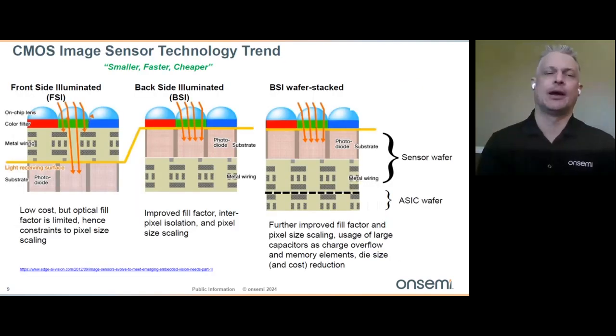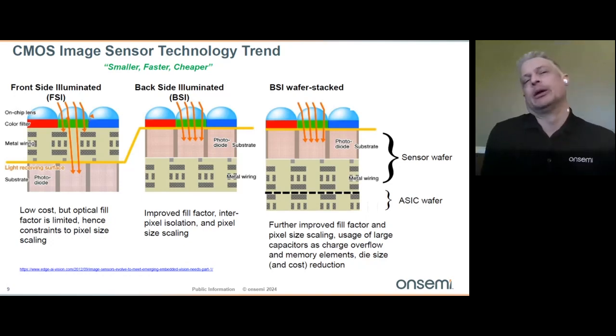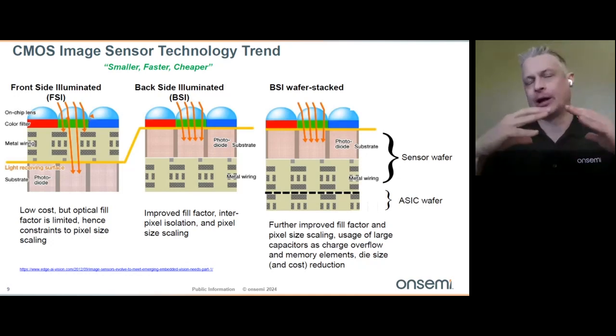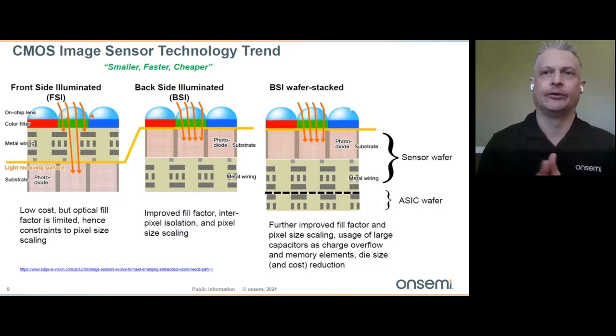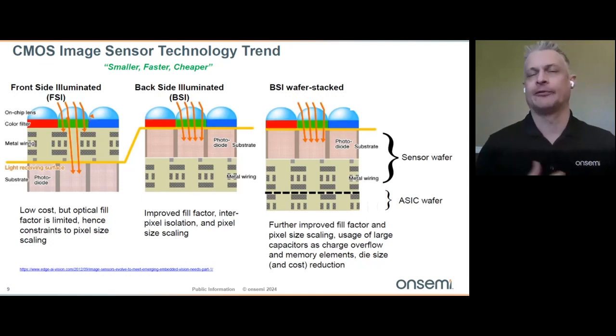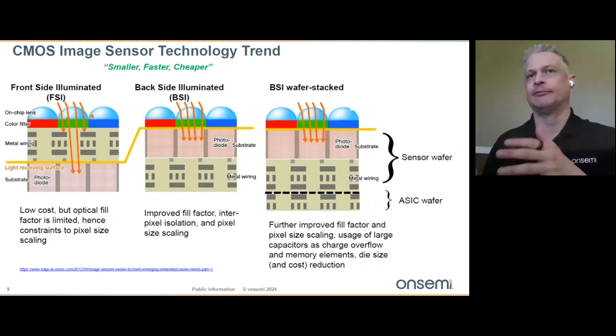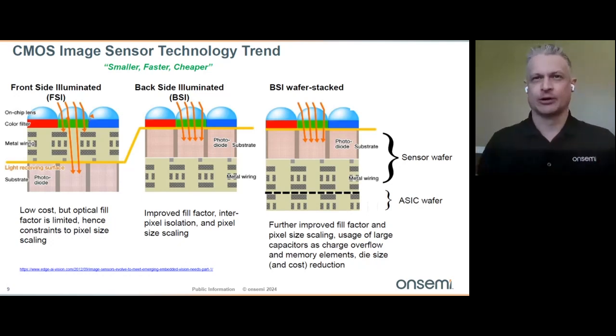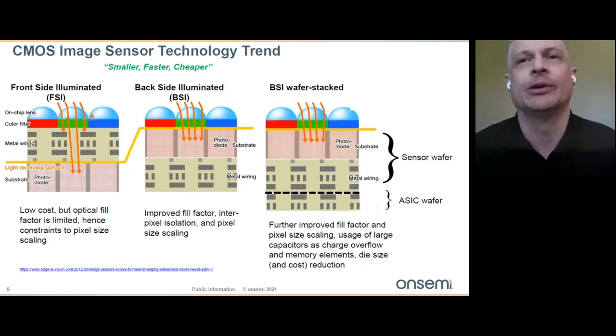And then this is a slide I think a lot of people in the industry have seen, but for those who haven't and really just want the top level knowledge of how the imaging works, basically you have the pixel. On top is what you see, the micro lens. This is focusing the light, as I'd mentioned, to get into the actual sensor. You have the color filter array, and this is so we're filtering out for different colors, and then we can do a color reproduction. And then you have all the circuitry associated with turning photons to electrons and then electrons to voltage at some point. So this is all that circuitry. And then there are other complementary types of functions that we do as well.